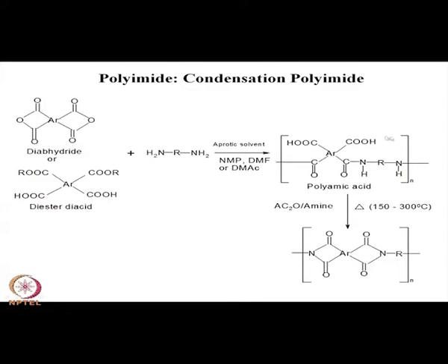So, this solution of polyamic acid should be used for soaking a fabric, then that polyamic acid soaked fabric, ply or layer can be heated at elevated temperatures from, say, 100 through 150, with the temperature increased stepwise, then up to 300 degree it completes the imidization, and the imide ring formation becomes complete. Once this imide ring formation is complete, it becomes insoluble and infusible.